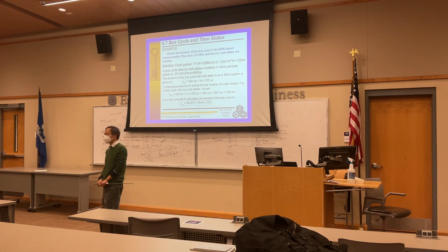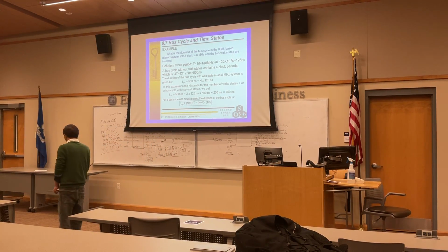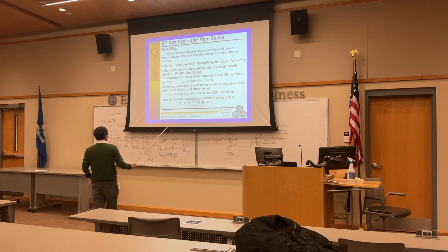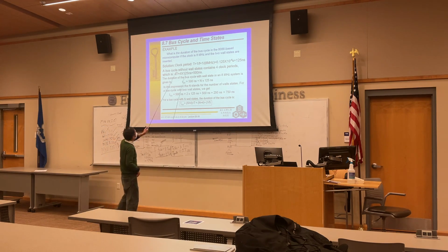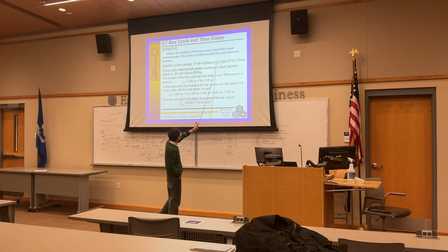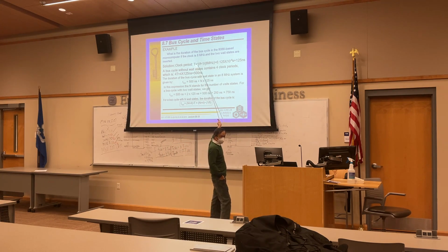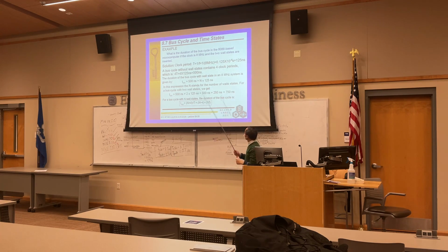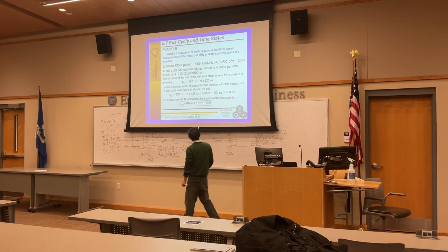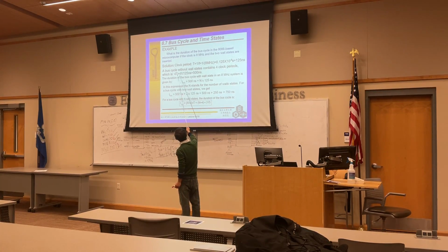4 clock cycles is a typical bus cycle, but sometimes we can introduce extra. For example, if the clock frequency is 8 megahertz, then you can calculate the clock period T, 1 over F, which is 125 nanoseconds. So your bus cycle of 4 T is 500 nanoseconds.